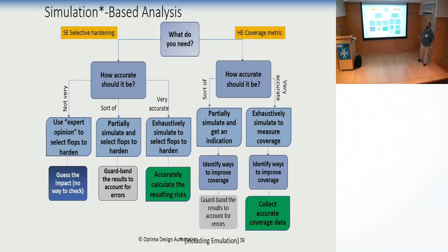Basically, the simulation-based approach, and simulation includes emulation. I will not go today into the details of why simulation is the only mechanism; we can go into more details offline. Right now, although we have some people here from the formal world who are working on formal solutions, the simulation solution is the main solution, and you need to do, using simulation, either selective hardening or a coverage metric.